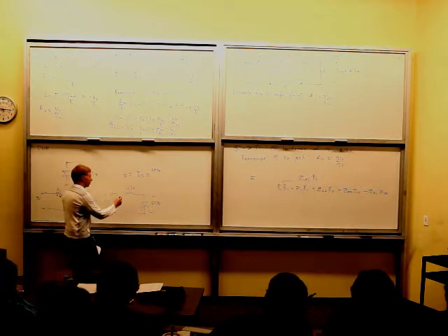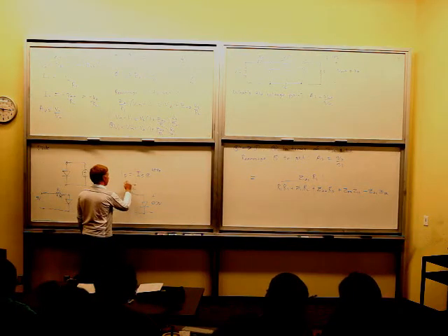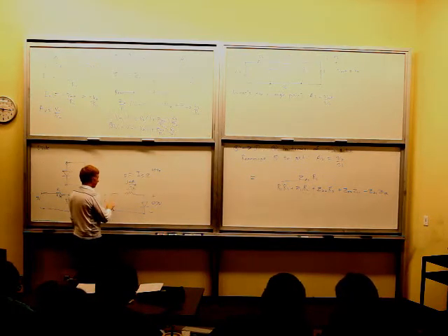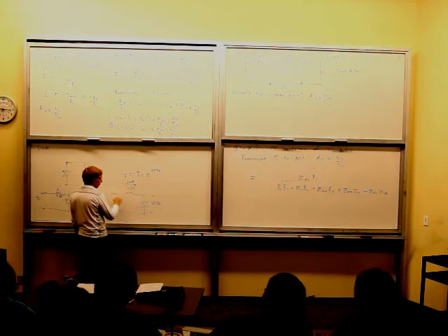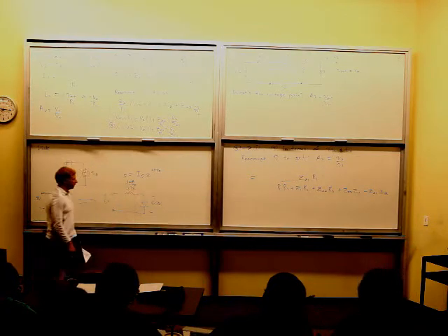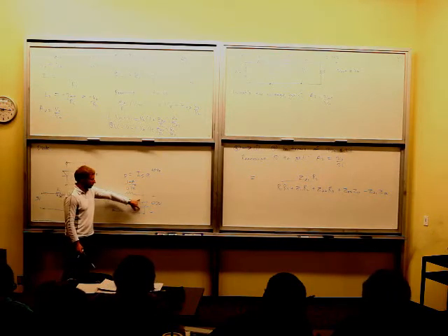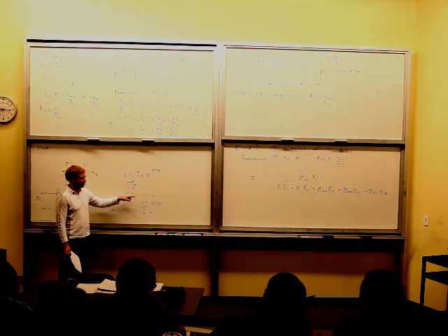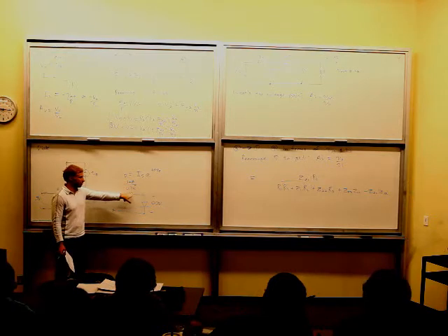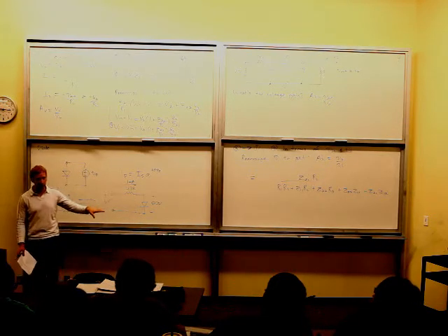That means that the current going through here is going to be 1 milliamp. So that's 4.3 volts: 5 minus 0.7 divided by 4.3K gives me 1 milliamp of current. Now it's relatively insensitive to that diode. That diode voltage will change a little bit, and it's really not going to change that current drastically because the current is now determined more by the resistance than it is by the diode.